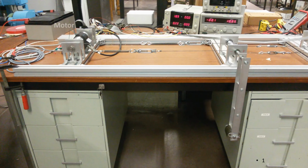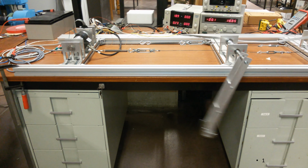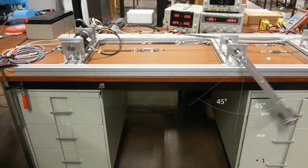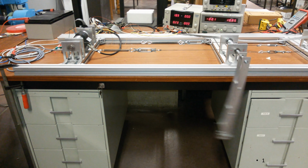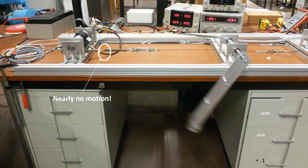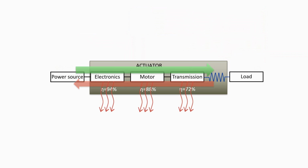On this setup, between the motor and the output link, we have two antagonistic springs, creating a series elastic actuator. The motor forces the link to follow a sinusoidal trajectory. We can see that the output link oscillates nicely with an amplitude of 45 degrees, while on the other hand, the input side is nearly standing still. In other words, the motor speed is near zero, and so is the mechanical power it provides.